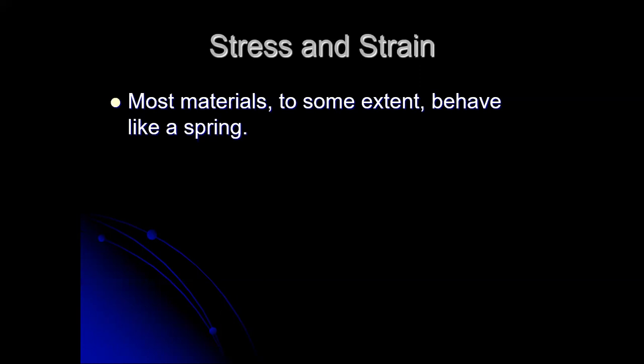Maybe it moves far enough to not be able to spring back. The material changes shape. All materials do this to a certain extent. When we apply a force to it, the shape changes. If we apply a tensile force, most materials increase in size. When we apply a compressive force, they shrink. Now, it may be very, very small. We might be talking about thousandths or even millionths of an inch, but it's a reaction.